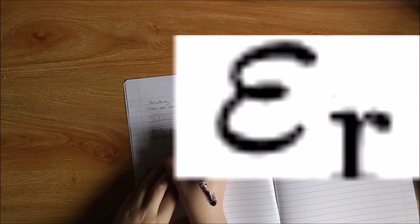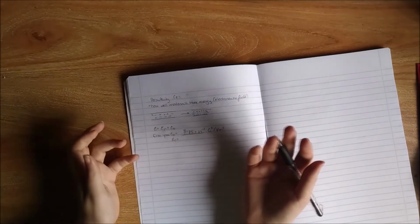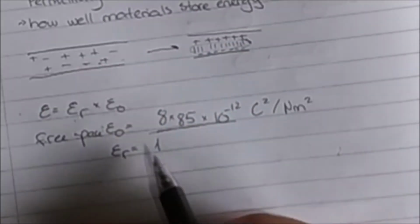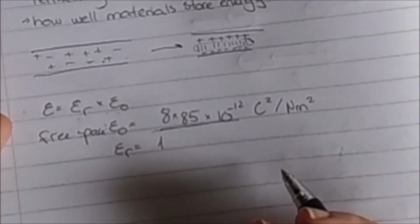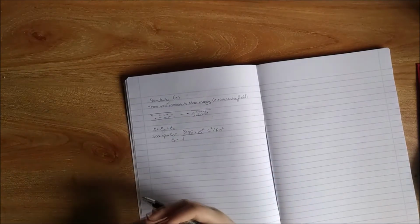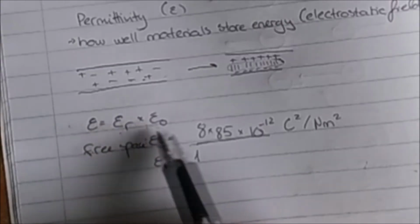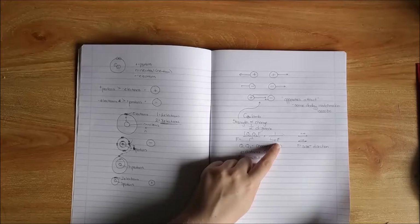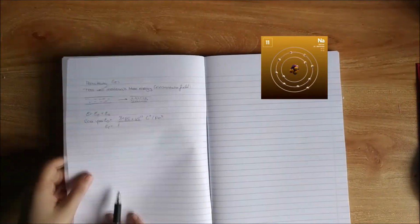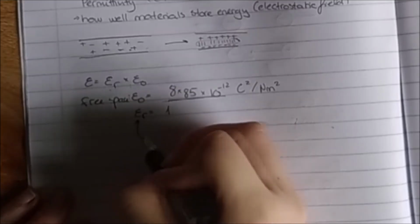Now, relative permittivity is based on the material that you have. So for air, that's 1. So you would just go 1 times that number and you have the overall permittivity. If you had water or something that would have something like 2.6, you would just go 2.6 times this value, and that is going to be put into that equation there. Yeah, dandy. So the one to watch out for is this one, because it's going to get different between different materials.